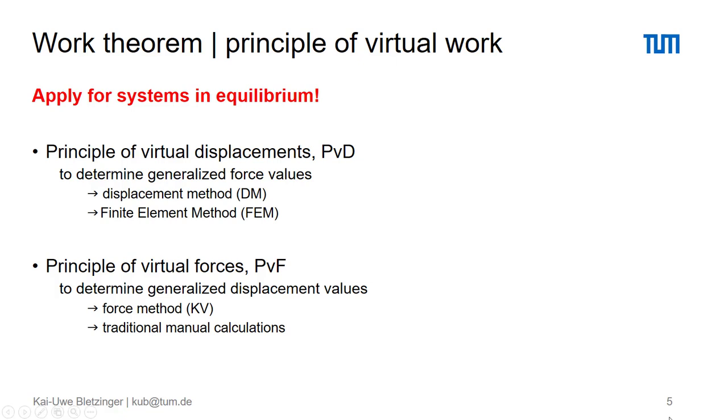The principle of virtual work comes in two variants: the principle of virtual displacements, the basis of the finite element method, used to determine the generalized force values, and the principle of virtual forces, used to determine the generalized displacement values and the basis of traditional manual calculations. I'm sure that you have learned about that in your basic education. Nevertheless, for the rest of this workshop, it's enough to concentrate on the principle of virtual displacements.